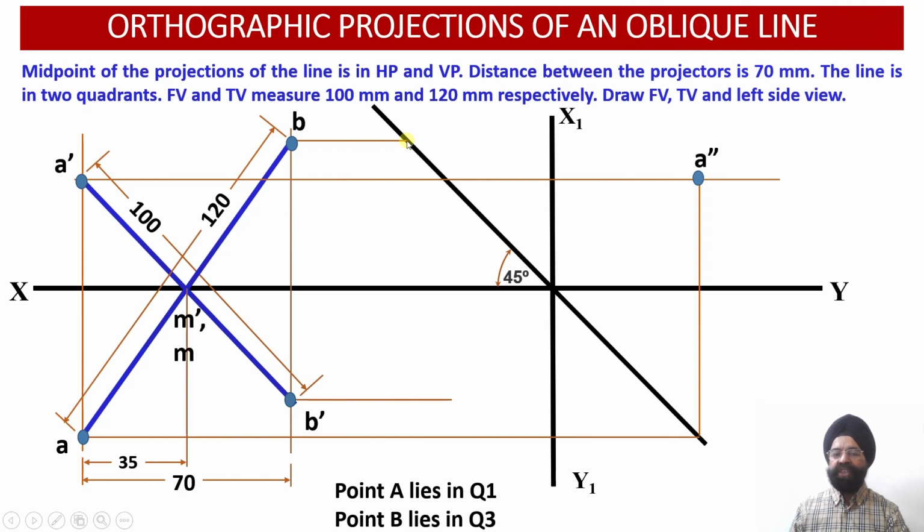And from this transfer line, we are going to draw a vertical projector line in the downward direction and extend this vertical projector line till it intersects with the horizontal projector line which had been drawn from the point B dash over here.